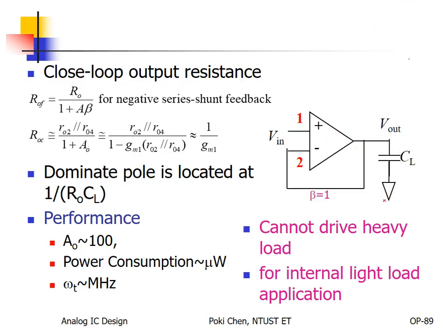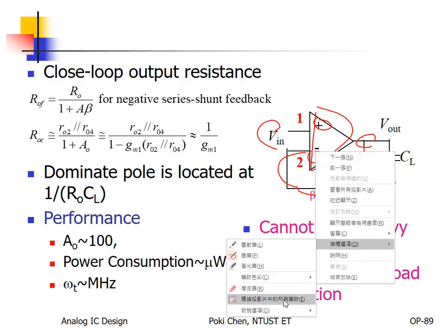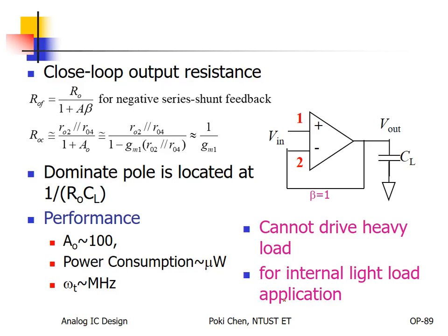Yeah, so you can connect your op-amp, never mind how much gain it has. We can connect V into the non-inverting input, and we connect output back to the inverting input. That's it. With such kind of negative feedback, usually you can much stabilize the overall operation, and also that close to 100% of the input will be delivered to the load. That's it. So what's the closed loop output resistance?